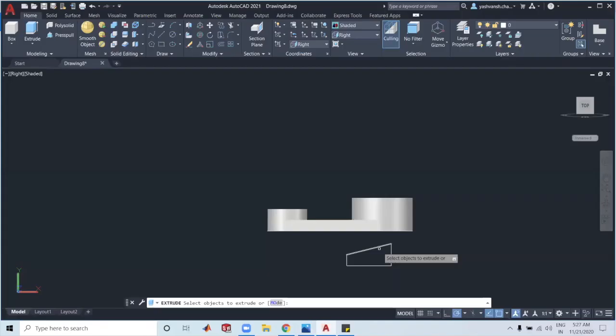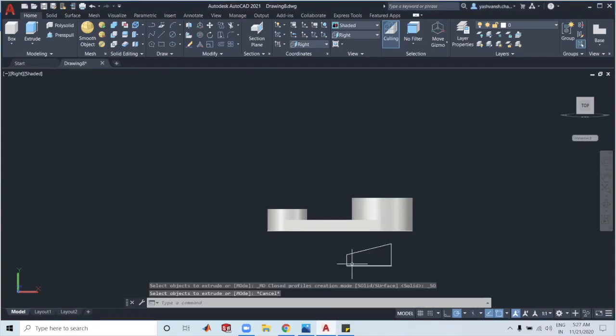So just like now, as you can see, this is one of the common errors which a lot of people make: when I try to extrude it, it doesn't really happen because the sketch entity is not combined. They all consist of separate entities. Okay, yeah. So they all consist of different sketch entities. They're not one combined entity.